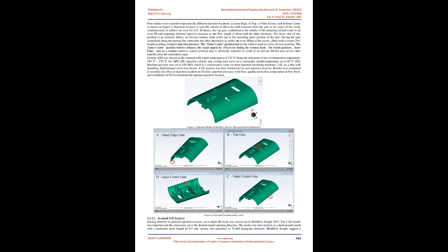13. Babu et al. 2016, worked on design and simulation of plastic injection molding process using ANSYS. 2 parts were modeled in Siemens NX 8.0 and a single mold base with interchangeable cavity inserts were designed. The flow analysis and simulation were carried out in ANSYS 15.0. The analysis resulted in the most suitable injection location, flow temperature, and injection pressure being established.